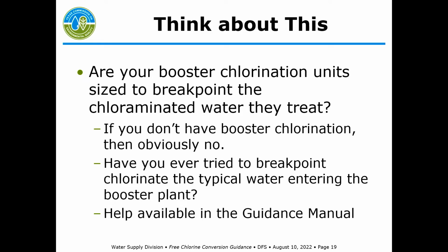Are your booster chlorination units sized to break point the chloraminated water they treat? And obviously, if you don't have any booster chlorination, then no. And if you do have booster, have you ever tried to actually breakpoint chlorinate the water entering the booster plant? And then, as I mentioned, in the appendix to the guidance manual, there's help to figure out, if it's not sized right, what size do we need, etc.